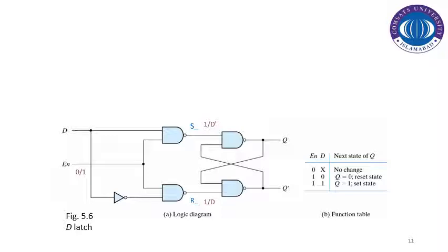We have to switch to another mechanism that is basically similar to the gated SR latch. If we eliminate the possibility of the same inputs at any time instant, the outputs cannot be the same for the rest of the combinations. So the D latch is the construction in which we can avoid this forbidden or invalid state, because this sort of circuit only has a single input D. The value can be 0 or the value can be 1.